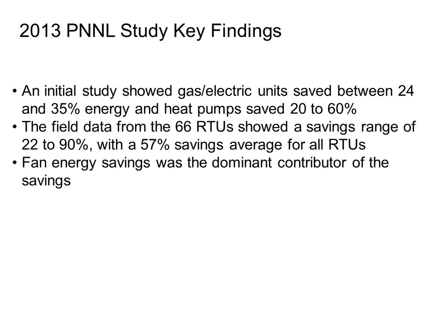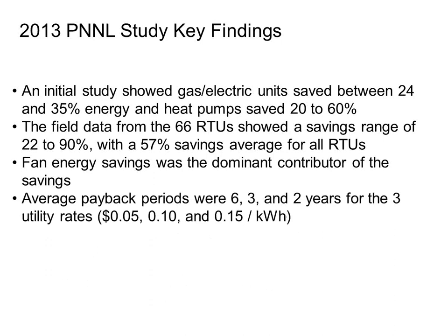Of all these technologies that they did, which were mainly economizers, DCV, and fan savings, fan savings was by far the dominant contributor of all the savings, right? And we already know economizers save a boatload of energy, and most of you guys have been hearing the DCV pitch for the past 10, 15 years, probably from me. And we know that saves a lot of energy. The fan energy savings by doing the staged air volume fans just totally rock starred it and crushed those other ones. So the dominant savings comes from fans, as you would expect.